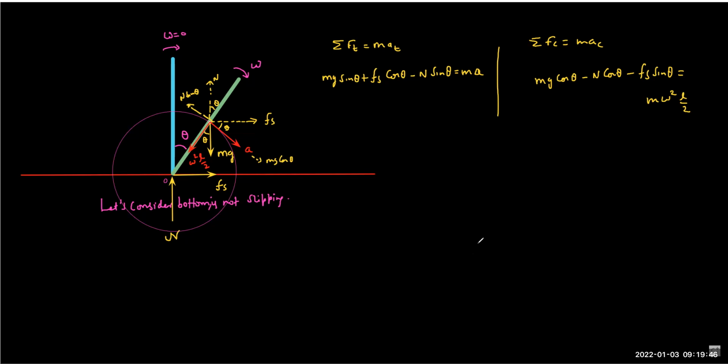Also, we can write the torque equation. About which point can we write the torque equation? We can write the torque about the bottom. But in this case, it is not advisable to write the torque equation because it's an accelerating body with some velocity, angular velocity as well, so things will be slightly difficult. But anyway, in this case we can apply. So torque about O equals I about O into alpha, because we are looking for alpha. Alpha is pretty easy to find.